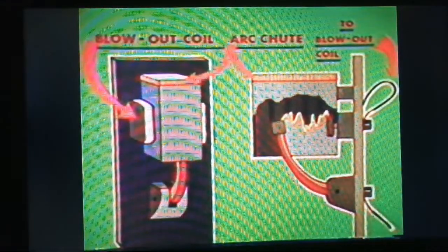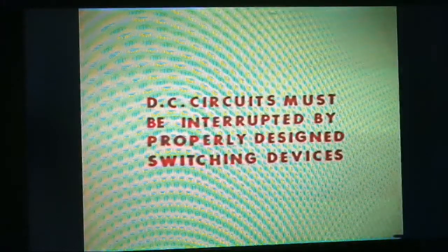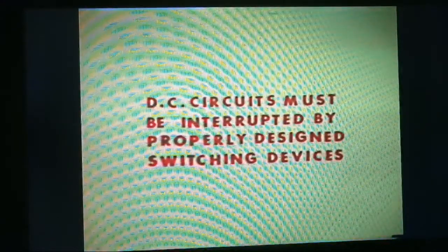The DC circuit breaker may include special arc chutes and magnetic blowout coils, which draw the arc into a long, interrupted path, stretching and cooling it. More about these devices, however, in a later lesson. One word of caution here. Only a circuit breaker designed for DC service should be used on DC circuits, and specially selected breakers should be used with inductive loads or high power circuits.